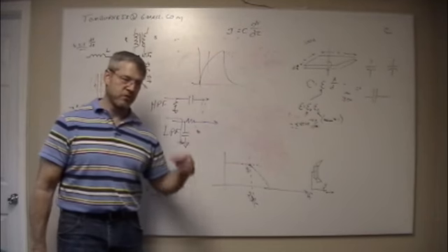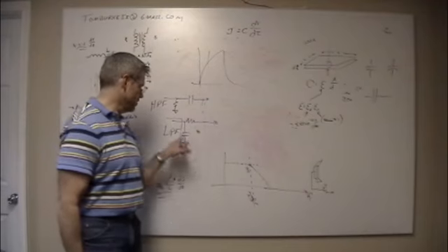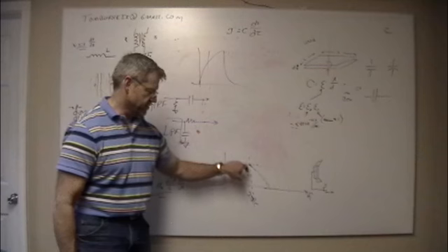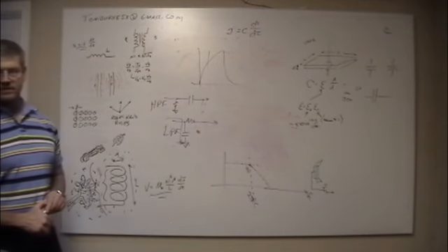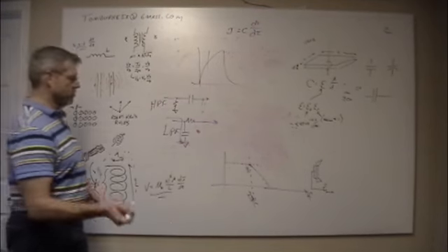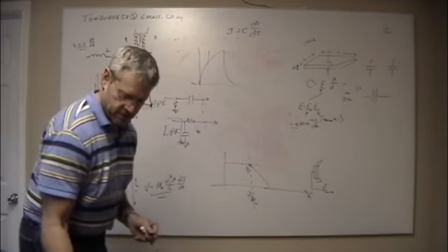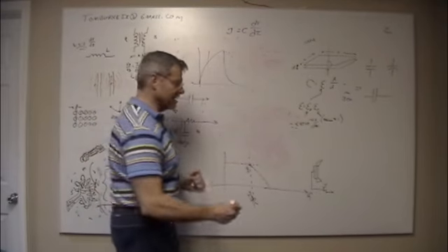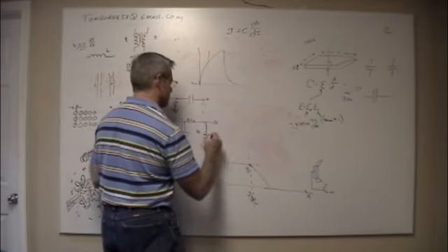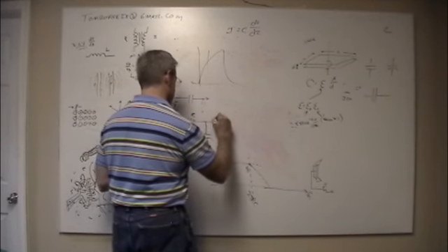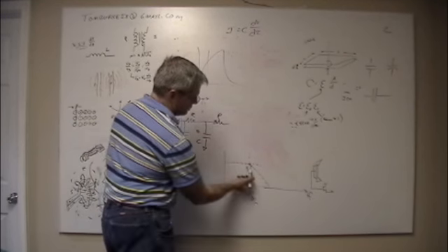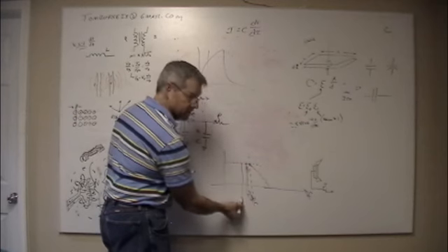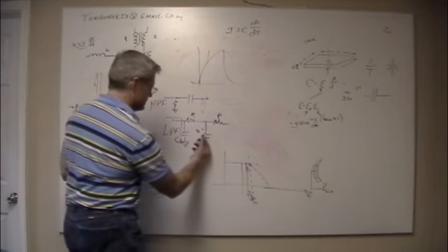So you start talking about a 1-pole filter, 2-pole filter, 3-pole filter. This is a 1-pole filter. And at F sub C, you're 3 dB down. Half your power is lost at F sub C. If it's a 2-pole filter, well, that's just, if you want to stay not clever, let's put it that way, R, R, C, C. Now a 2-pole filter will move this in to here. A 3-pole filter will move this in to here, and so forth. It'll move your frequency to the left.